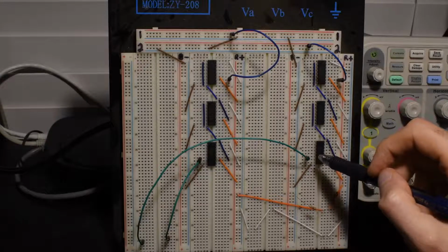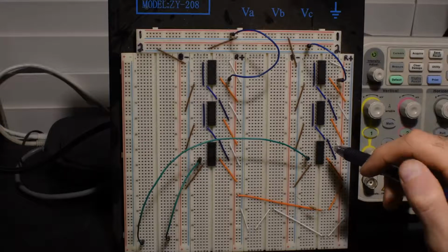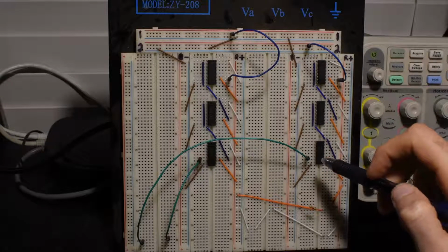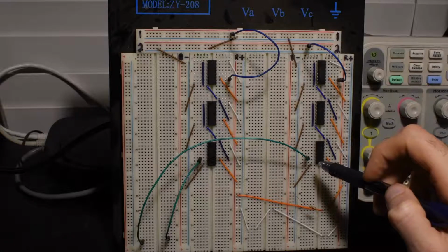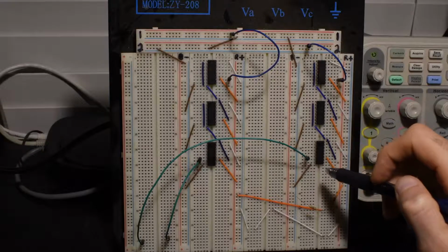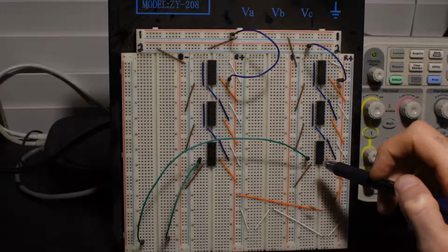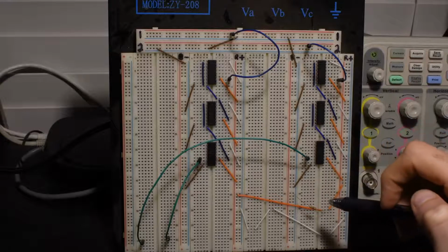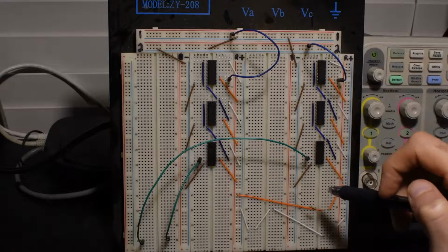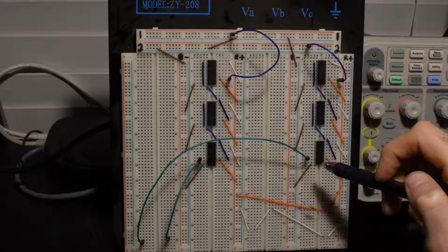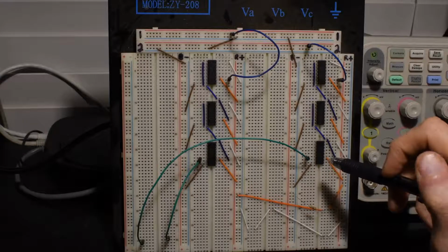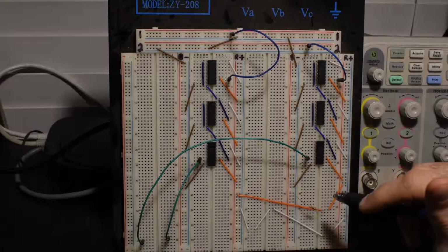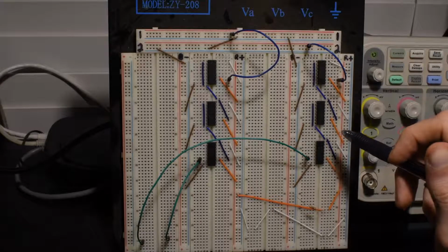The only real limitation, or one of the main limitations, of this is that we can measure some really small frequency differences, but we're limited to averaging over a 13.4 second interval. For this case, that's going to work fine, because from the initial tests we did just looking at the oscilloscope, the frequencies don't change much over that time interval in the case we're interested in. But that's basically how it works.